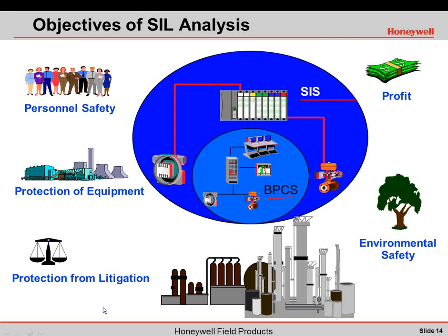That's where the safety portion of the process control system comes from. Now, if that fails, for whatever reason, the operator didn't respond to the high alarm, and the high-high alarm was supposed to shut down the system and didn't, then at that point the safety system comes into play, and it should shut down the process through its separate means in order to maintain the safety of the overall plant. Right?